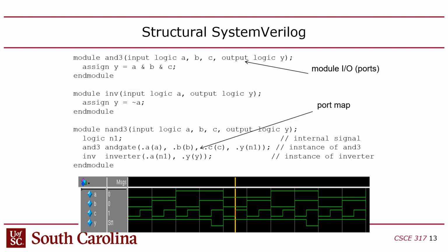You guys ever use an oscilloscope? So like an oscilloscope, generally you set the trigger to be like a rising edge that meets some threshold. So you have a signal and you say, when that signal hits 3 volts, trigger, right? It's the same thing here. You can say, whenever the write enable of this signal is 1, I want you to then start capturing. And it'll capture every cycle until it fills some buffer, whatever the depth of that buffer. So you could set it up to like 1024. So you say, whenever write enable is 1, capture 1024 samples, once per cycle. And you capture it, and then it sends out those samples on JTAG, right? And then you'll see them in a waveform.